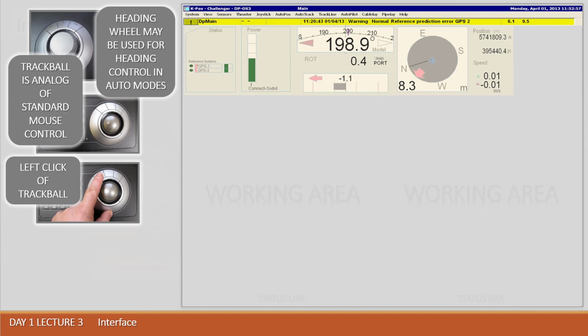Next zone, what you see is a force plotter area. Here you can see the vector of produced force in green, and then the wind sensor selected to give the data to the model. In my case, wind sensor number 1. Then you can see the wind vector acting on the vessel, and the current vector calculated by DP. In our case, DP current vector, all other forces which are acting on the vessel. And the